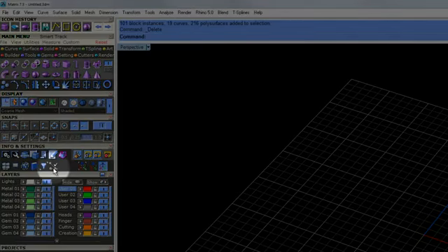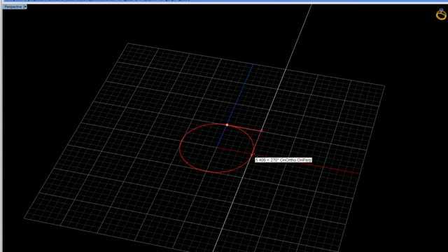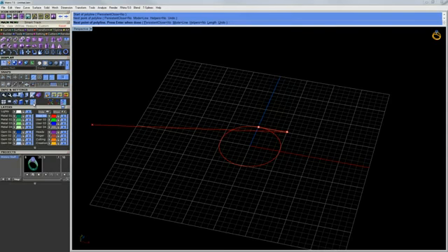And then we have Smart Track. If anybody has ever used Smart Track in the past, we give you a simple toggle on and off for Smart Track. So if I start working here with Smart Track on, when I go to, for example, draw, you can see it's giving me my ortho lines. If I were to turn on some different O snaps, it will start to give me these different grid lines and Smart Track options available. All right, so this is just a simple toggle on and off for Smart Track now within Matrix.